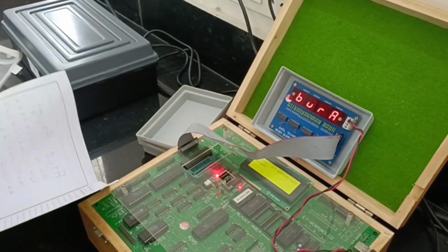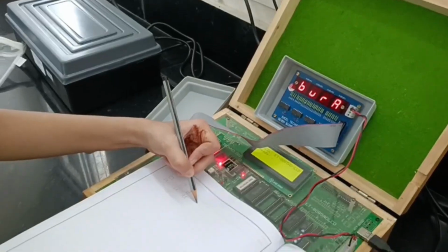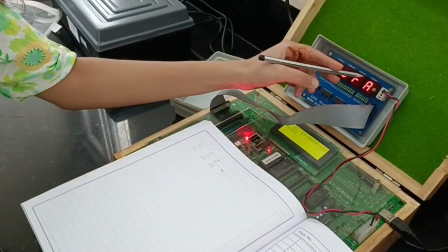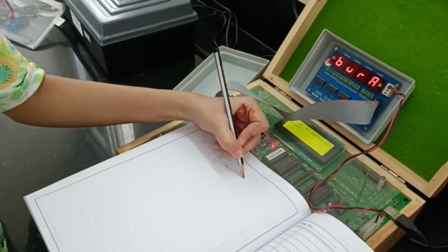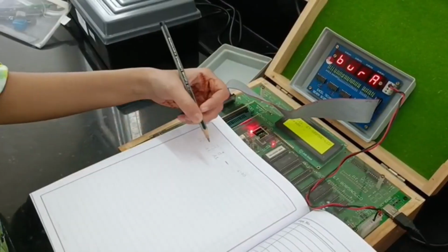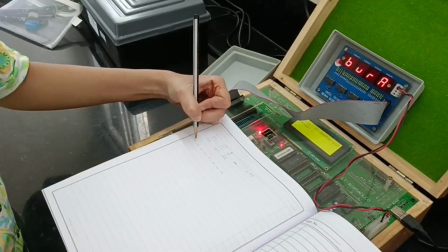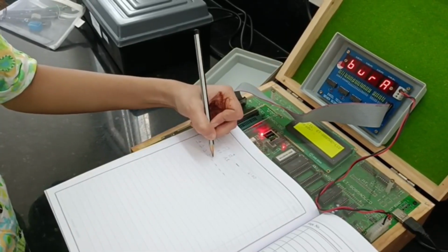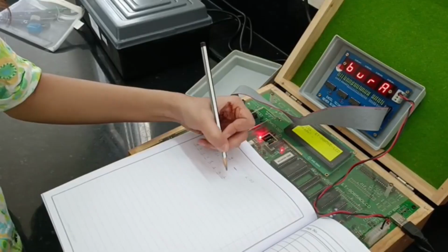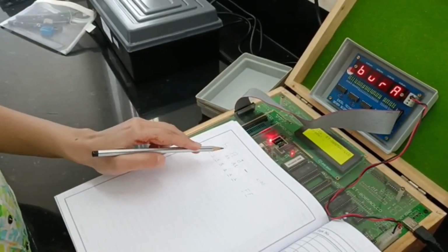If I want to still type in English BAD, then I will have to not use this display, which is display 1, which corresponded to the address 2100. So I have to turn off all the lights for this, which means all the positions have to be 1. 1, 1, 1. All have to be 1 for it to turn off, which is FF in hexadecimal.